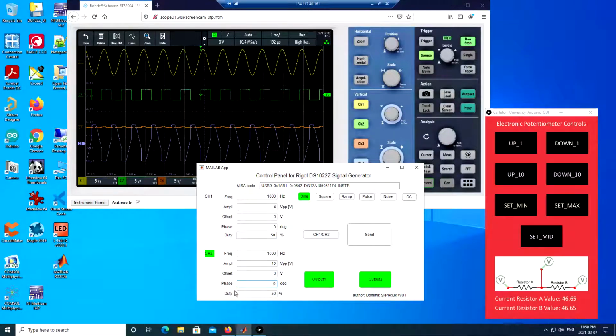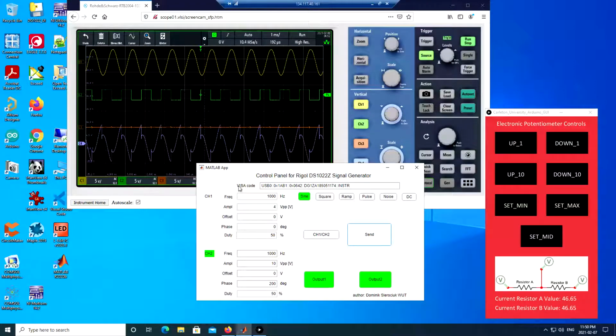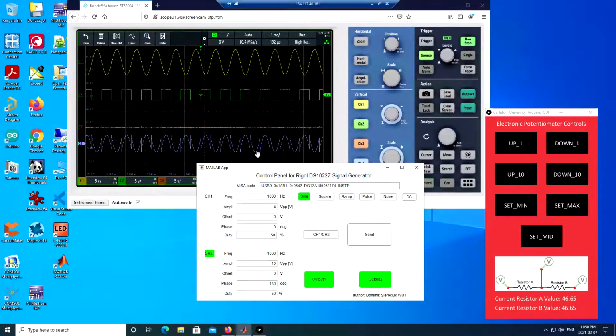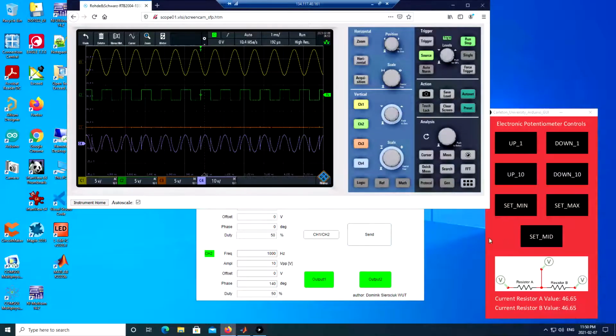So let's start at 200 again. See what my waveform looks like. That's where we were before, and it looked good, but maybe go down a little more to 150. Oh, and now we're really getting something that we are used to seeing. So maybe drop that down to 130, see what it looks like. Now it looks like we're at the opposite sort of side. So maybe 140 is the kind of sweet spot for that one. And it looks like it is.